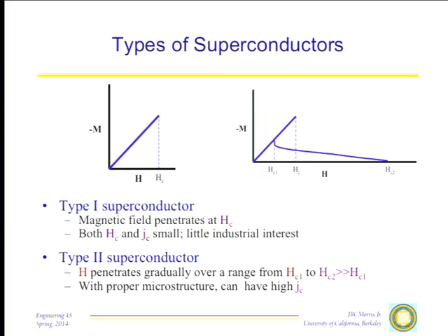And people had discovered that if you took niobium, you could get it to carry a decent critical current. And if you deformed it by drawing it into a wire, for example, the critical current would go up. So John Wolf had the, turns out, really clever idea that if he could take niobium and get the dislocation density to extremely high values, he might get an even better critical current. So he came up with the idea of taking a niobium tube.